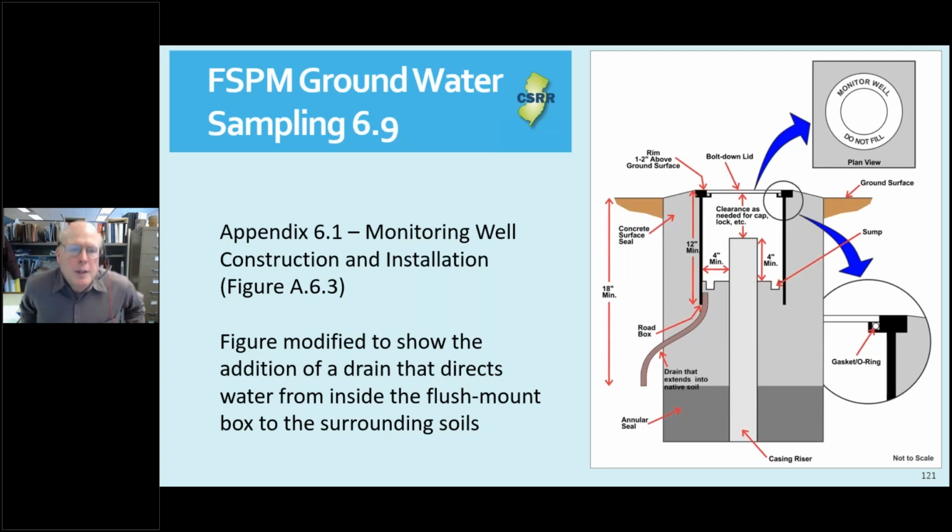In review, DEP has shown that how you sample, when you sample, and where you sample can affect your sampling results. So information like sampling method, sampling date, sampling depth, and sample turbidity should be key to the sampling results. To facilitate appropriate purging of a well and reduce the potential for undesirable levels of drawdown from occurring, it is recommended that an accurate recharge rate of each well be determined.